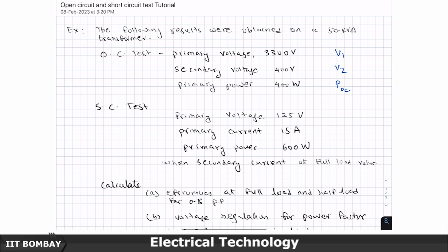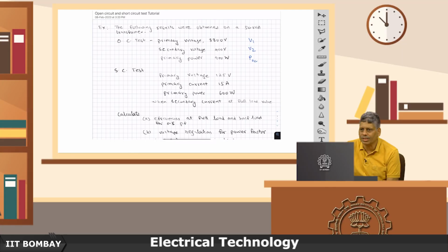But the magnetizing current here can be ignored, because the voltage developed when full rated current is flowing through 1/20th of the rated impedance will also be 1/20th of the rated supply voltage.